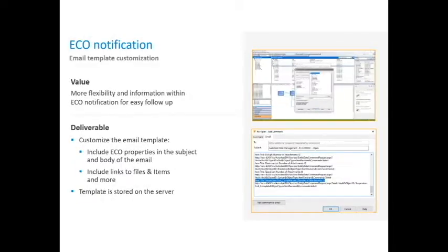All right, some of our customers have been asking for the ability to customize the ECO template. If you're using Vault Professional, this is just a professional tool, there's an engineering change order system built in. Throughout the process we create routings to different people to sign off on changes that are happening to certain drawings or certain files. So these automatic emails get sent around, and that gives you links to be able to open up the drawing right from there. But you want to get the appropriate information on that particular email, so we can customize that now.